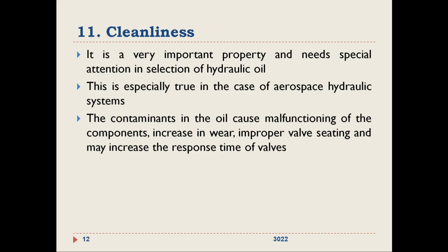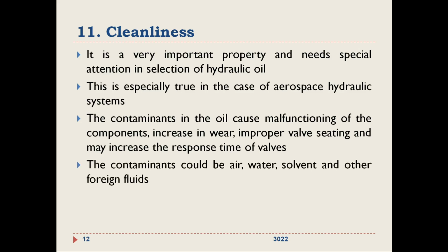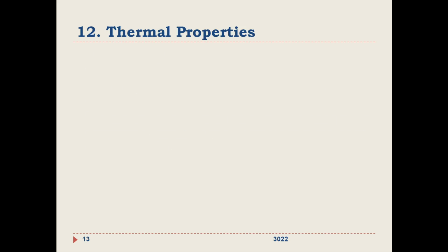If the valves are not seated properly, it will affect the operation of the valves as well as the movement of the piston and all. Also, it may increase the response time. So it will affect the entire system. Many contaminants, foreign particles like air, water, solvent, and other fluids, are contaminants affecting the cleanliness of the hydraulic oil.